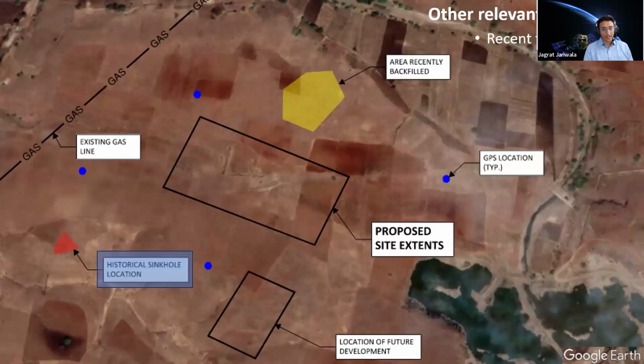Then recent failure locations. So I've utilized InSAR for sinkhole predictions. And visualizing historical sinkholes helps in understanding what the typical patterns are that form right before a sinkhole formation. And it also gives you an understanding of where to monitor well, and if there were any remedial measures, where those remedial measures were performed.